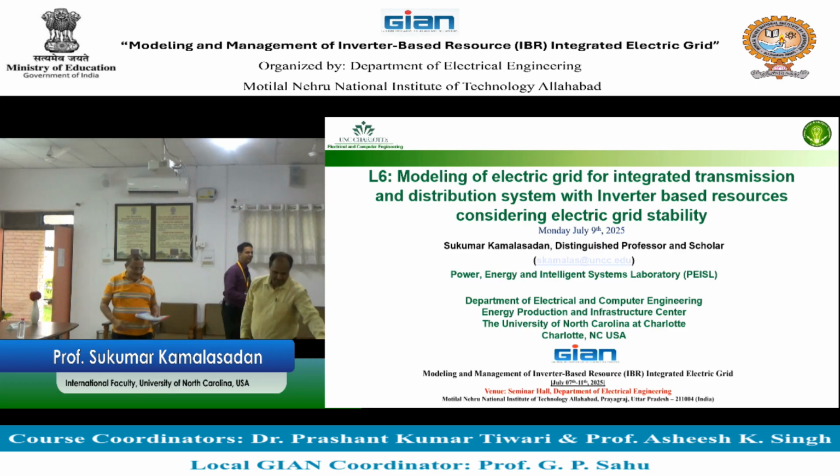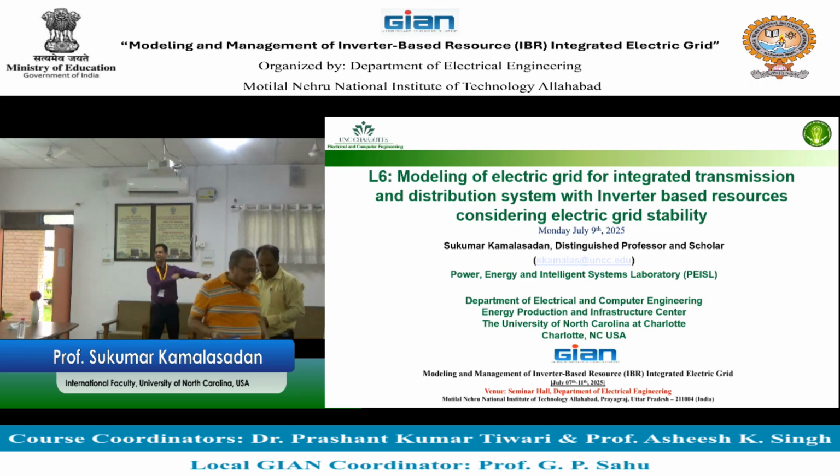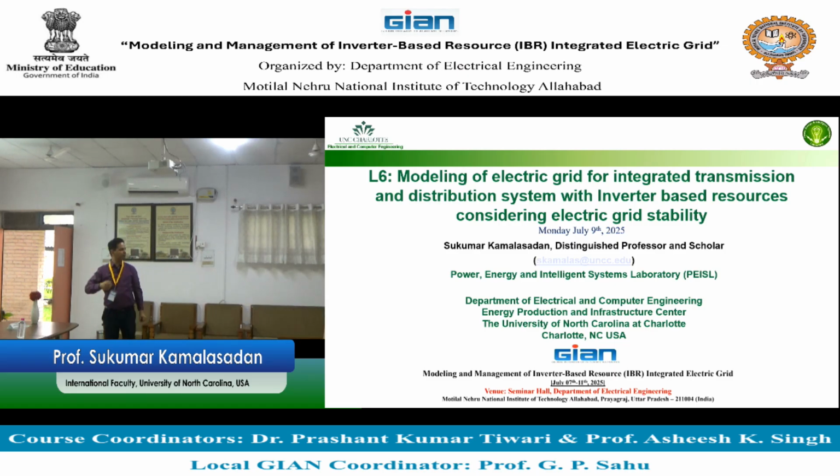So if you run the power flow every 30 minutes, what happens? You will be able to see the voltages of electric grid when the load changes, right? Because every 30 minutes or every 10 minutes, 15 minutes, the load keeps changing. So you can run the power flow again, and again, right? Such power flow running every 30 minutes is useful for electric utility. Why? Because you can now know what are the changes in voltages in different points when the load varies.